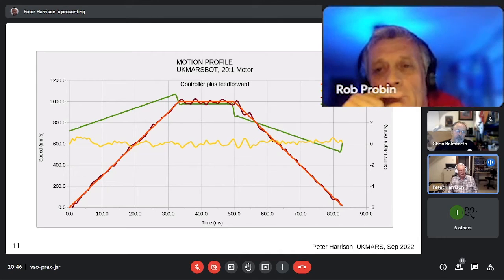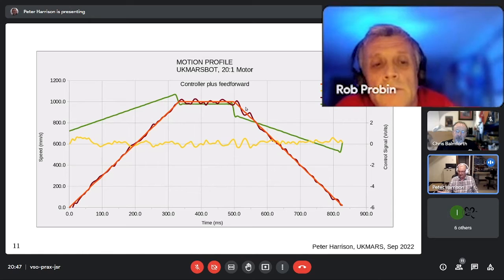All these things are true. The poor sensor resolution is largely what's responsible for these oscillations that you see. Right, because it's only doing like 3 counts per millimeter, whereas on my contest robot Decimus I've got, I can't remember, 100 times that. And so the opportunity to get the answer right is much better. The lack of precision means that there's going to be some oscillation.